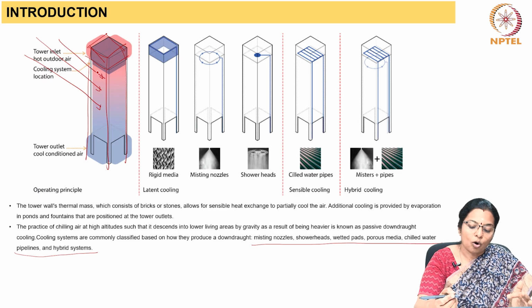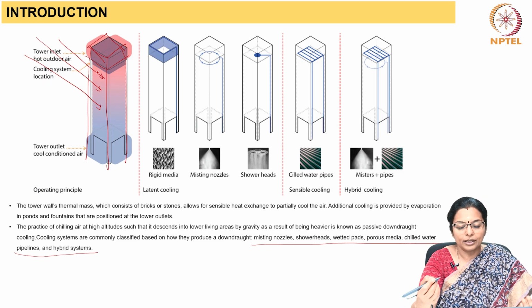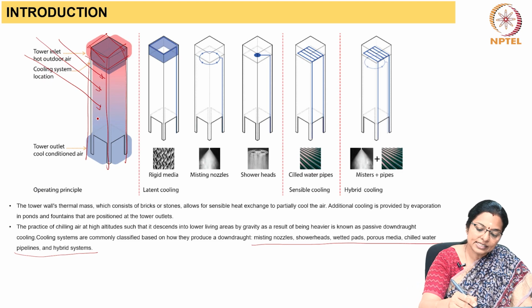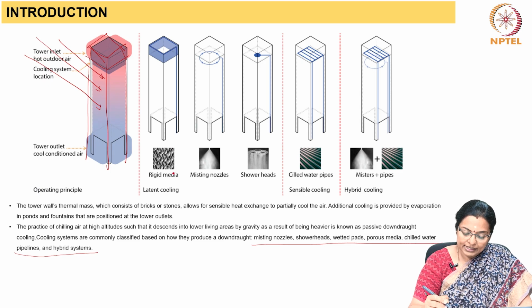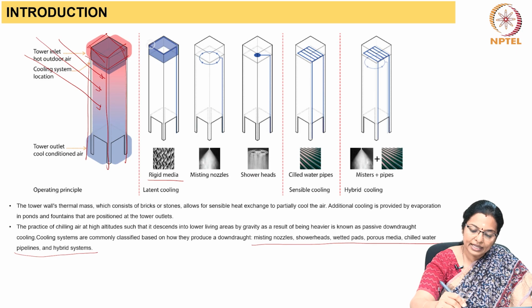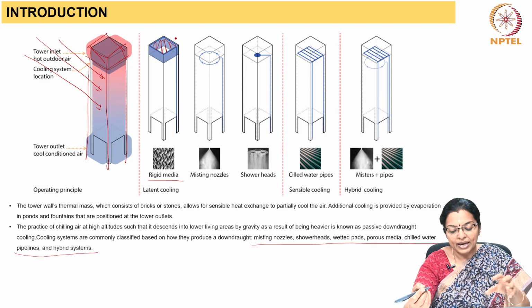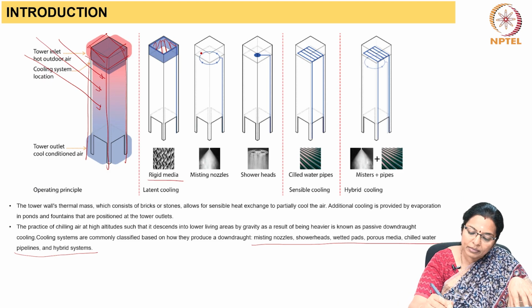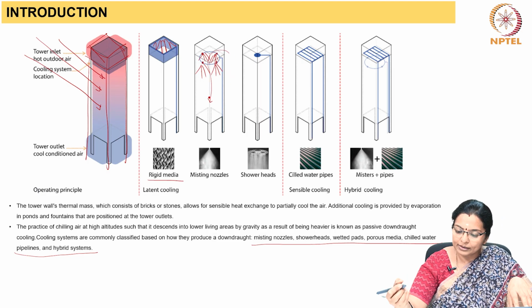Now, in order to add humidity to the air inside the tower, there is sometimes a rigid media here, which makes the air moist, or sometimes there are misting nozzles which spray water, and the air which flows here becomes moist.